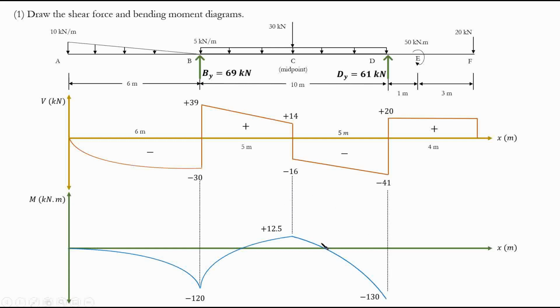But let's take a look at this. First of all, as you see, the intensity here is small, right? And then the intensity gets up. Of course, when I'm talking about the shear value, I'm talking about the magnitude. The magnitude here is small, and here it is large. So here we have a flatter slope, and here we have a steeper slope. So we start with a flat slope and go steep, right? These are flat and this is steeper. Flat and steep.